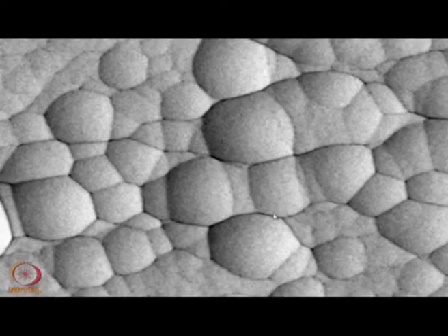However, during this joining process we have a lot of surface defects and flaws. For example, this is one pore. With such, we have so many pores that they can be easily detected without any difficulty. Here we can see it is almost like a sphere, and we understand that this is not a wetted surface. When it is properly wetted, we should have a flat surface, but it is almost